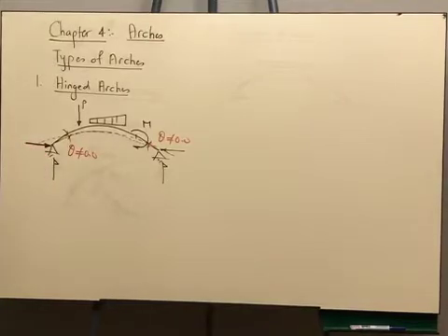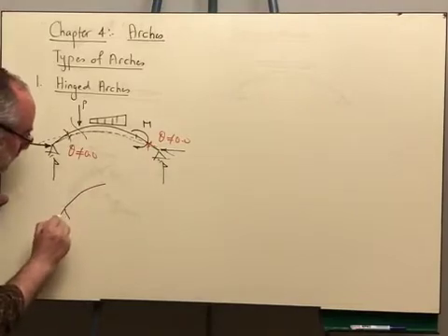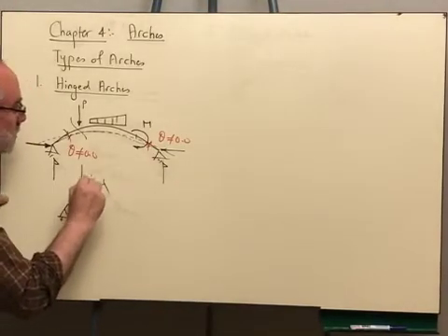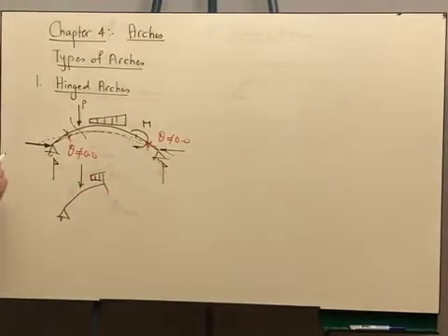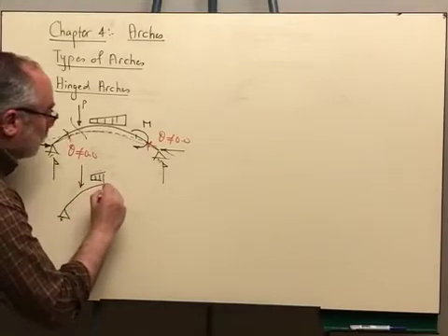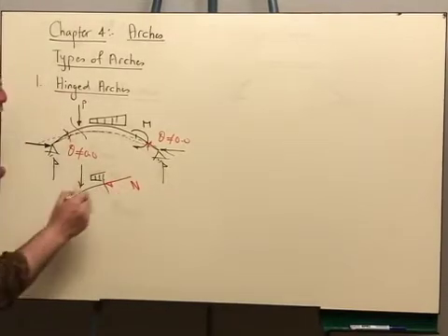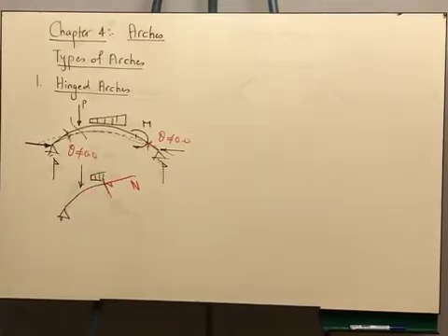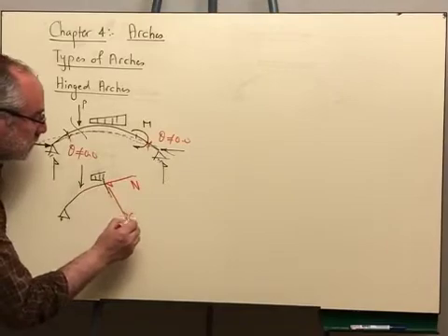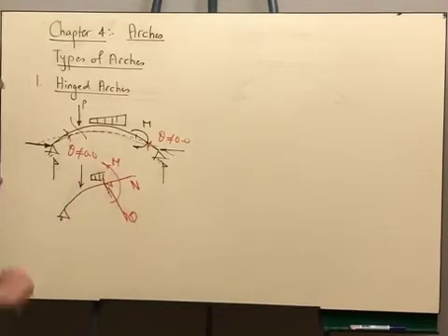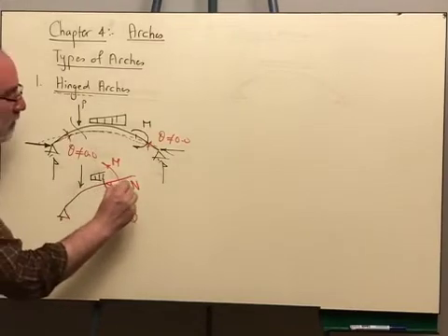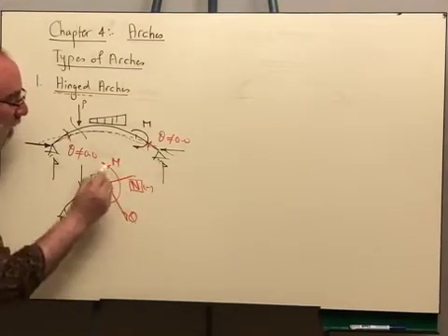According to this, whenever you are cutting a section in the arch, unlike any beam, for example, this is my section, like that, what will be the internal force? The internal forces here will be normal force compression. Notice that the normal force is perpendicular to the section. And there will be shear also, and there will be bending moment. So in the hinged arches, we are going to have the 2 ends hinged. There is rotation at the 2 ends. Whenever you are cutting a section, you will have basically normal force compression, and you will have shear and bending moment.